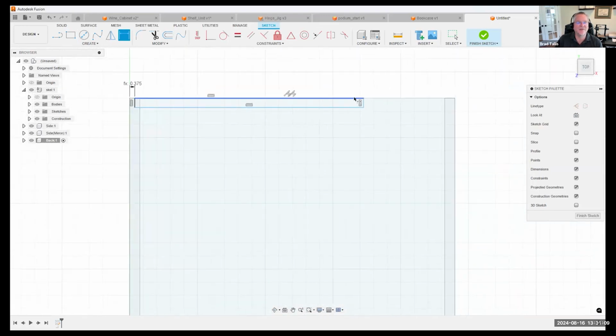Okay, and then I'll do the same thing here. I'll click on that existing dimension. It's going to reference it, so I don't have to type in that formula again. And then the last thing it wants to know is how thick is this? Well, I'm going to say it's plywood divided by 2. I want that to be a smaller back. Okay.